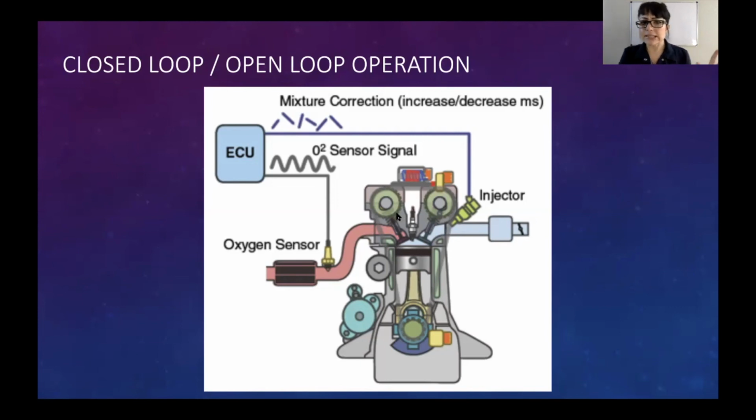So the circle is the ECU, also known as the PCM, which, by the way, is another thing OBD2 commanded. They standardized it, so everybody calls it PCM. Now some vehicle manufacturers may still want to be rebels and call them ECUs, but if we see ECM, engine control module or electronic control module, ECU, electronic or engine control unit, they do the same thing. Anything that has control in it is going to be a control module. So our ECU is going to command the output, a fuel injector, right?